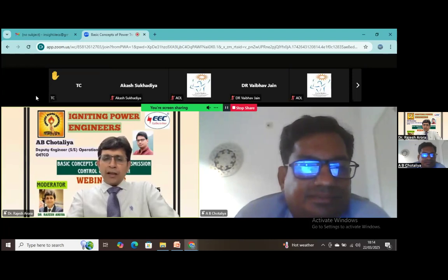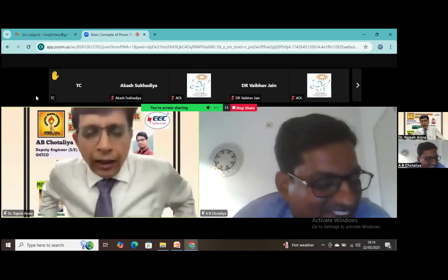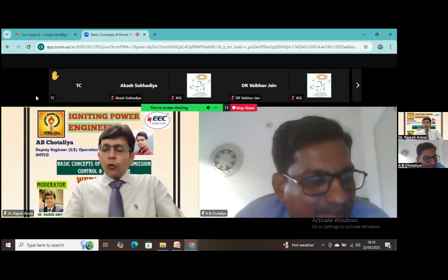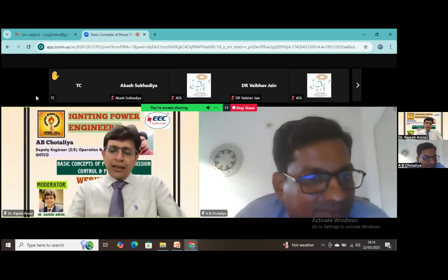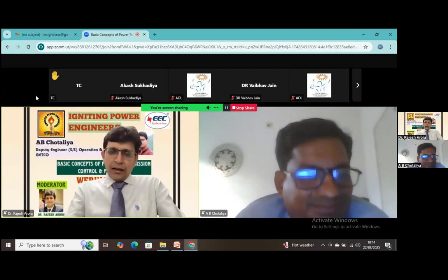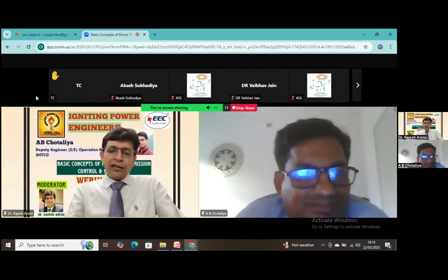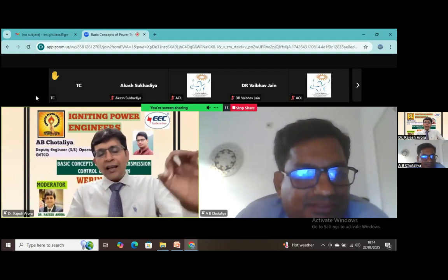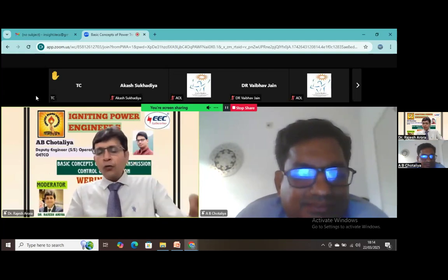Abhishek ji, would you like to answer or should I answer it? When you are not using the fuse, you have replaced it with an MCB. In both cases, the important thing is the proper rating. First of all, you should understand the total burden of that circuit, and based on that, you have to select the MCB or the fuse.